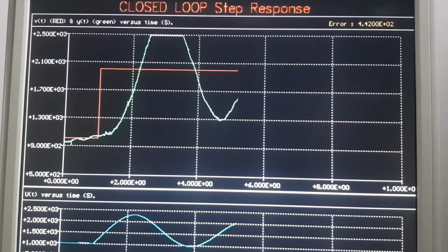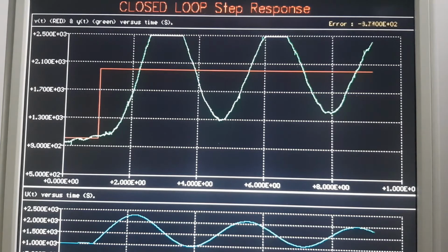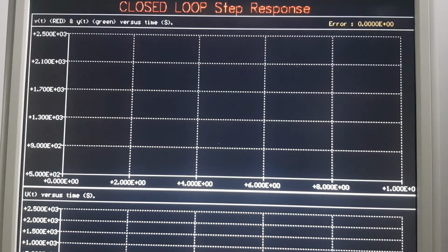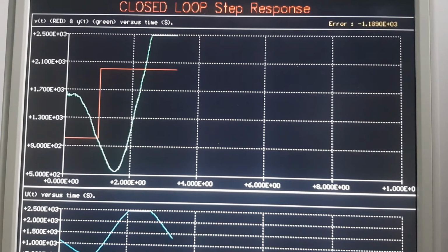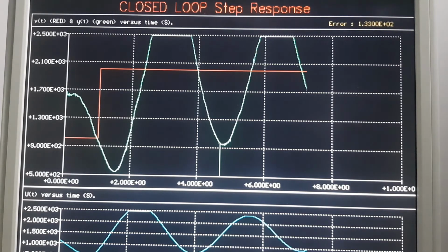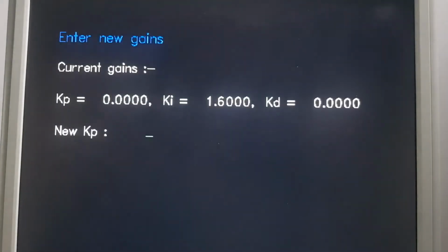Now it's almost gone into a limit cycle, like the previous one. This is exhibiting not very good behaviour at all, characterised by this signal here forming a limit cycle. In that particular case, we would say that this had gone marginally stable. So the integral control has gone marginally stable about this value. We'll have to reduce our integral control to get back to our nice controller.